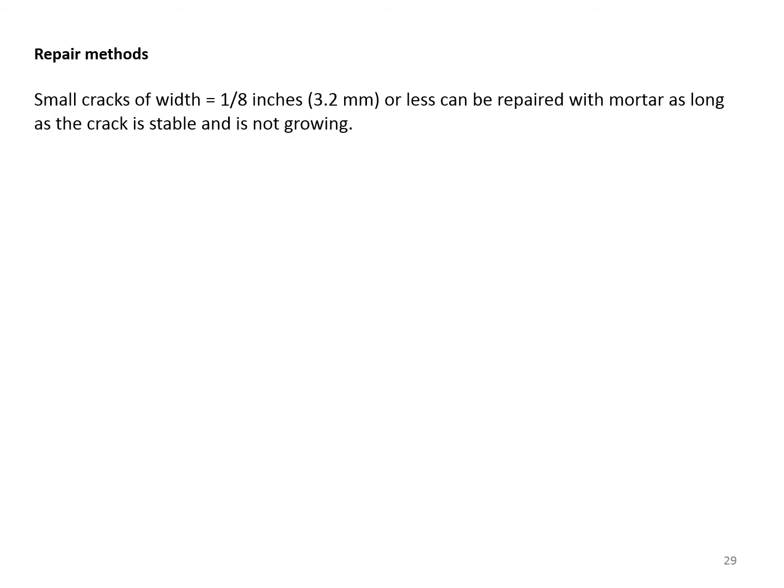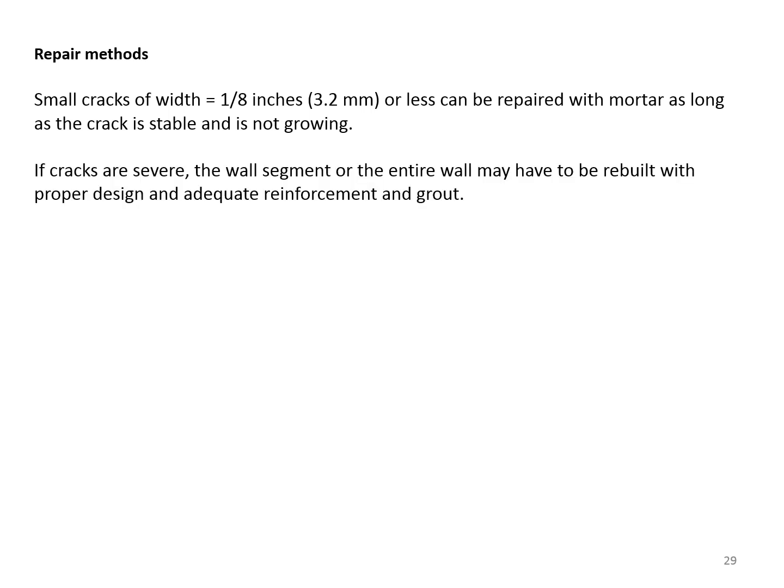Repair methods. Small cracks of width about 1/8 of an inch and smaller can be repaired with mortar as long as the crack is stable and is not growing. If cracks are severe, the wall segment or the entire wall may have to be rebuilt with proper design and adequate reinforcement and grout.